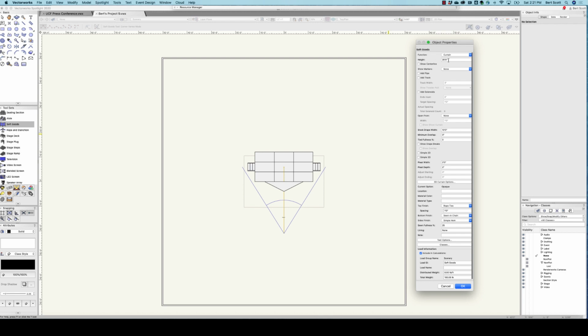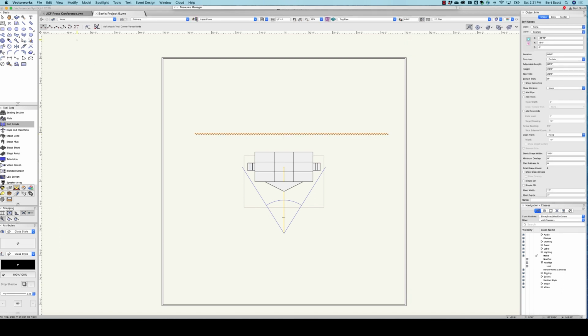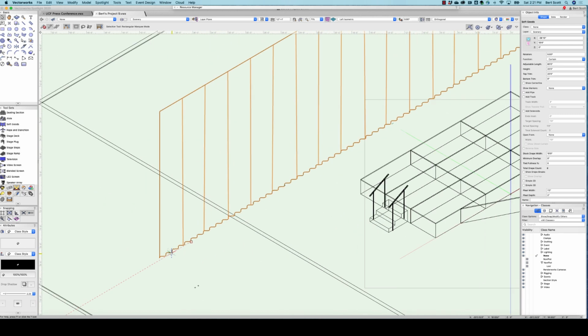That's the default. Mine's left over from creating this previously, but you want to change it to 20 feet. And then the pleat width, I don't know why this defaults to 2 feet, because a stock pleat width is 12 inches or 1 foot. So we're going to change that to the stock. You can leave everything else the same and click OK, and it will think for a moment and then give you this wavy line in 2D, or in 3D it is in fact a pleated curtain.